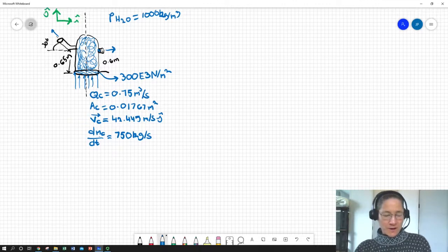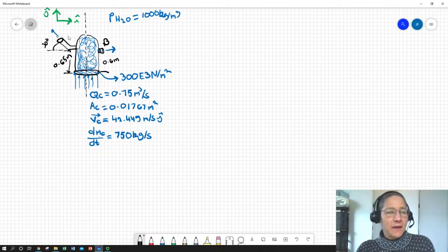Now, we can use the same argument over here at our other points at B and A. We go from fluid that has pressure, but it's a little water molecule sitting right here. It's not going anywhere. It's just sitting inside the hydrant. Then when it moves from this point to right here, it gets a whole lot of velocity. Wow, change of momentum, force acting on it, action, reaction, and there we go. We've now got a force that we're going to use to set up our statics problem.